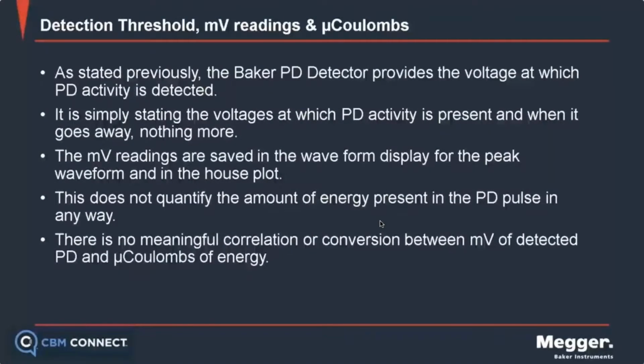And when it goes away, there's nothing more. We're not evaluating the energy level that's consumed by the partial discharge. While that information might be helpful in some regards, primarily in design and trying to mitigate partial discharge, for most of us, from a reliability professional standpoint, we don't really care much about that. We just want to know, do I have PD or don't I? And if I do, then I can take some actions to improve the quality of my services, or improve the quality of my vendor, my OEM supplier for my motors, or perhaps my installation practices and my switchgear, my cables, or all the different things that can cause PD.